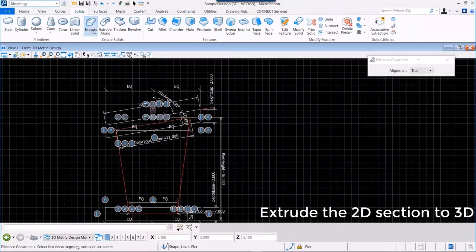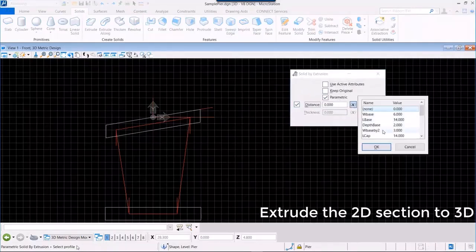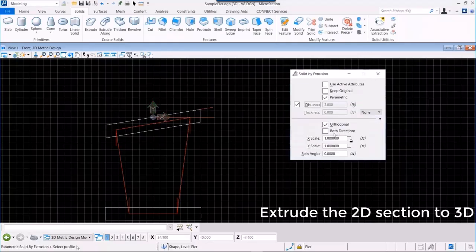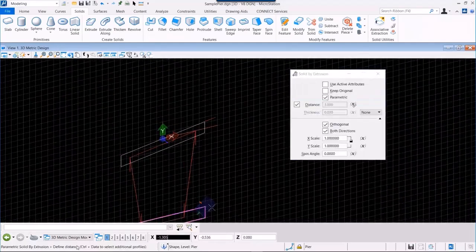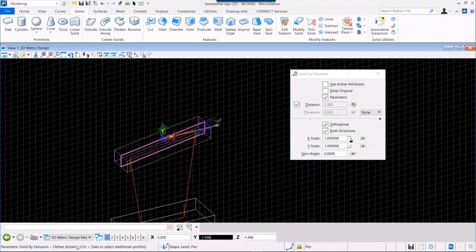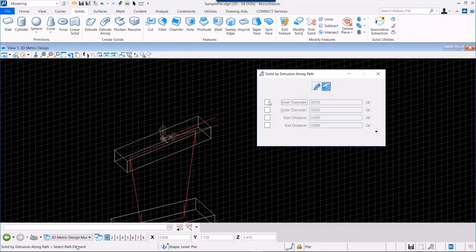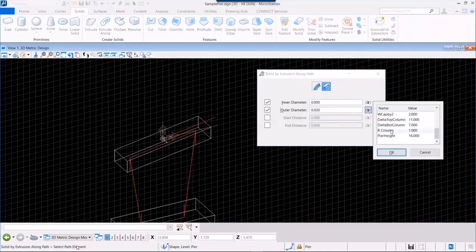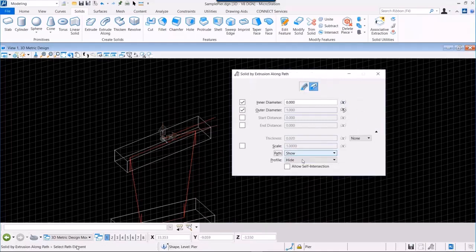Then after that, we can say, okay, the 2D elements are done, they behave properly. So now let's give it some depth, right? And this is not that parametric, it's just solid by extrusion, right? So we just say extruded at a certain distance, and that's the variable, right? Remember, I mentioned the center lines. So basically, I just say that is half of the cap, half of the width of the footing, and the columns too, right? Define that. So again, it's solid by extrusion.